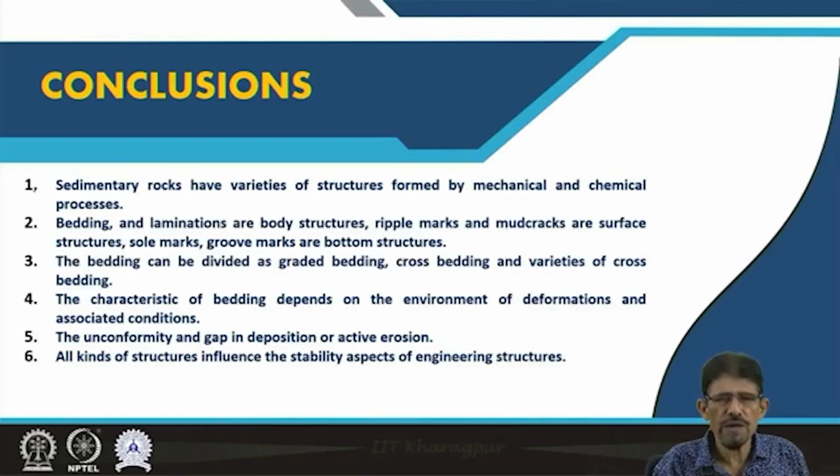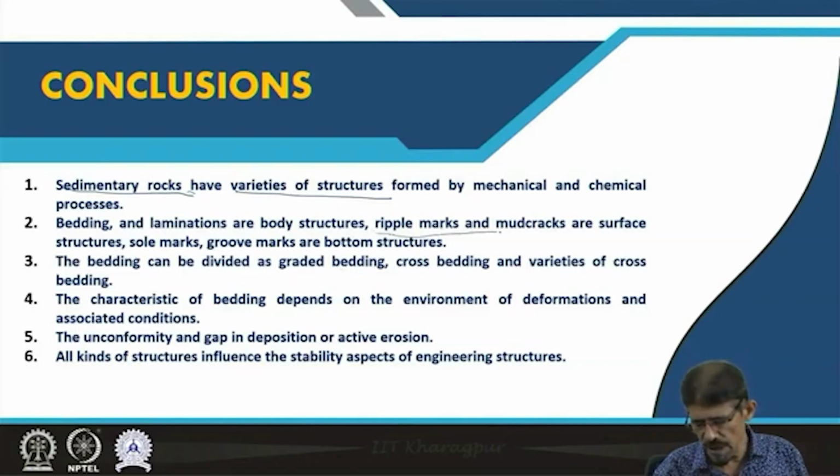Friends, in these lectures we have elaborated on sedimentary rocks, and sedimentary rocks have varieties of structures formed by either mechanical or chemical or biochemical processes. The beddings and laminations are body structures, as well as some shallow surface structures where the ripple marks as well as lamination, mud cracks, bird footprints, raindrops, animal footprints, etc. are the surface structures.